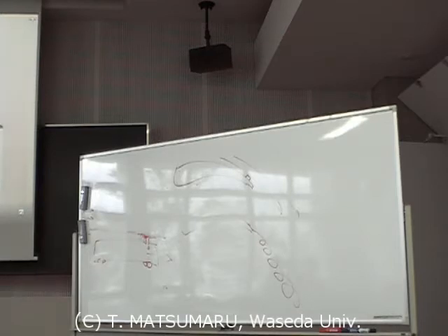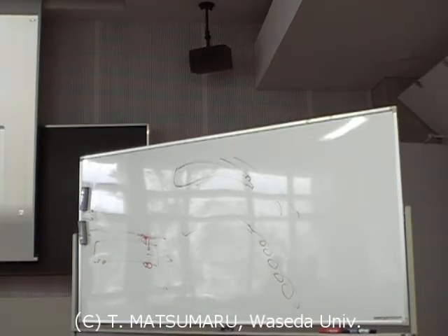Now, if you transfer this concept to a curved surface like this, you can imagine that this flow will try and stay attached to this curve the whole way down. So you'll end up with a flow path like that. This leads to our two main regions of flow. You can characterize most flows as separated or attached. This is an attached flow, as it follows the surface. A separated flow will move off from the surface and go over here.